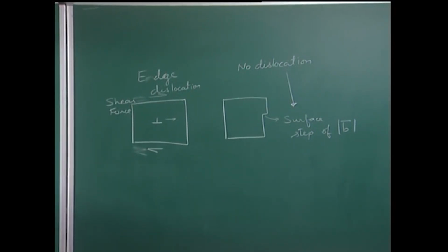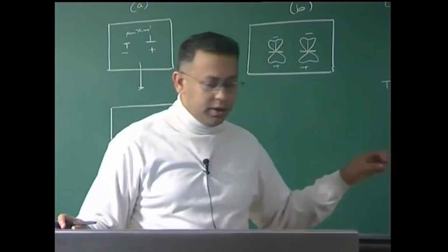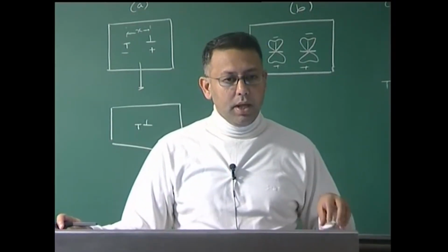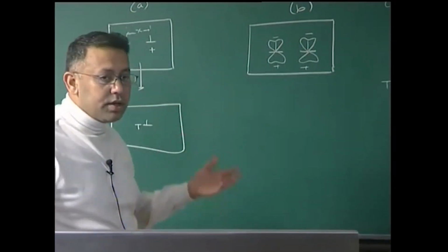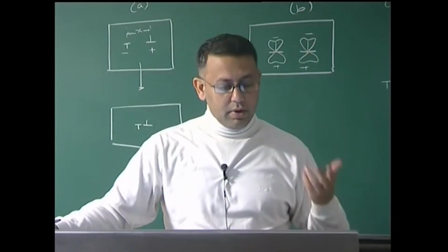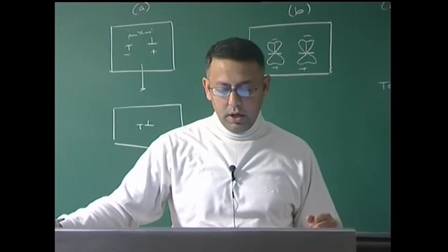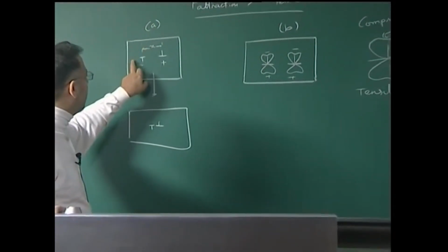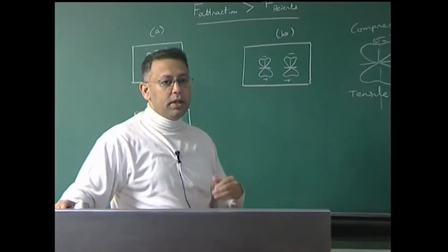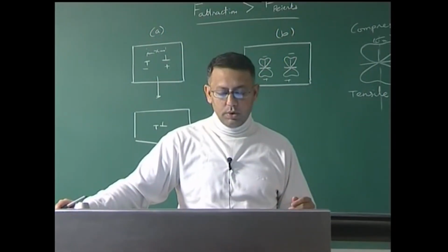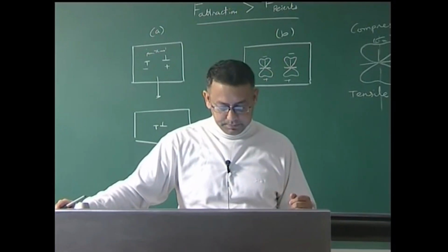Now, when I am trying to understand this, in this example, I can take an isolated defect, I can see its interaction with the external constraints or the forces I am applying. Then I can take a pair of defects, then I can understand how this system is going to evolve given this pair of defects, and the parameters I would like to track during this is obviously the combined stress field. In other words, in this case of course the overall stress region decreases because of the cancellation of the compressive and tensile regions, the energy as the dislocation structure evolves, and of course in some cases, as I told you, there may be charges also involved which I need to track.